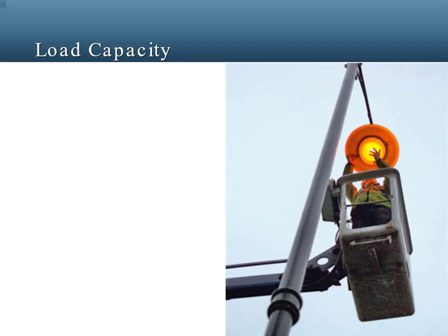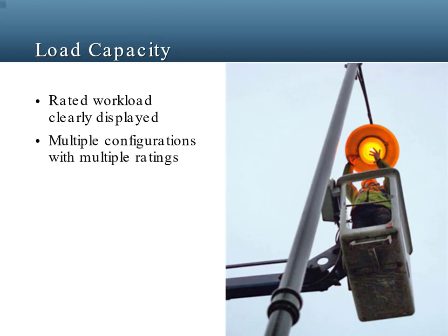Load capacity is another important design issue. The rated workload capacity must be clearly displayed on the work platform. Most aerial lifts have a single capacity listed because the equipment is fairly simple. However, some of the more complex aerial lift devices have multiple configurations, each requiring a different workload rating. Be sure to review the workload for the various configurations and never exceed the load capacity indicated.